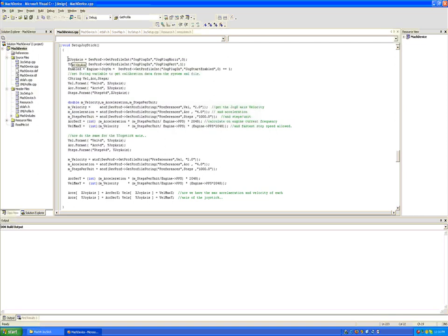First thing I want to do is fill variables to tell me which axis I'm currently using for each movement of the joystick. I do that very simply with a devprof getProfileInteger jog plugin jog plug horizontal with a default value of 0. If you look in your XML file, you will find these key words. Under the heading of jog plugins, you'll find a variable called jog plug horizontal.